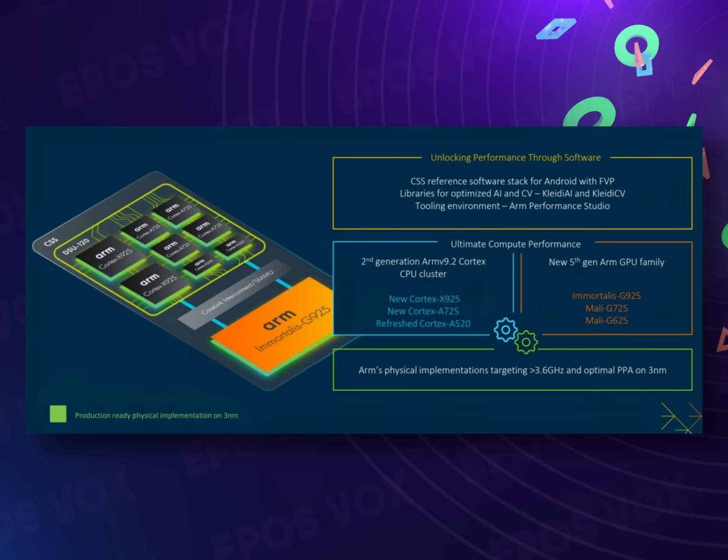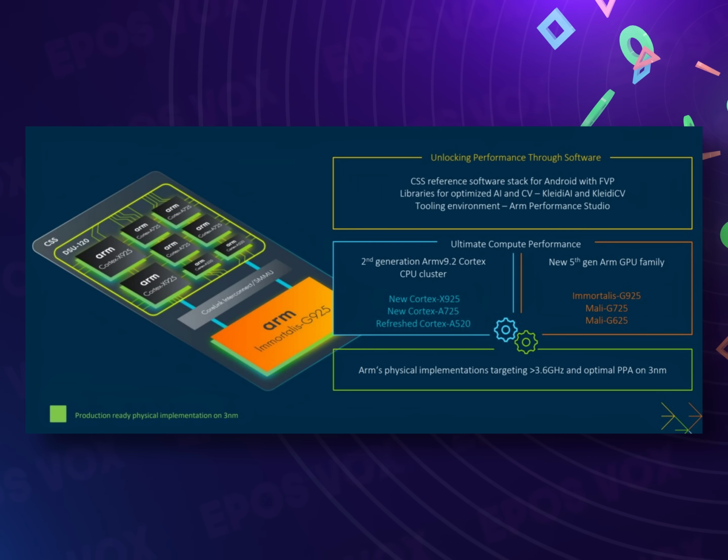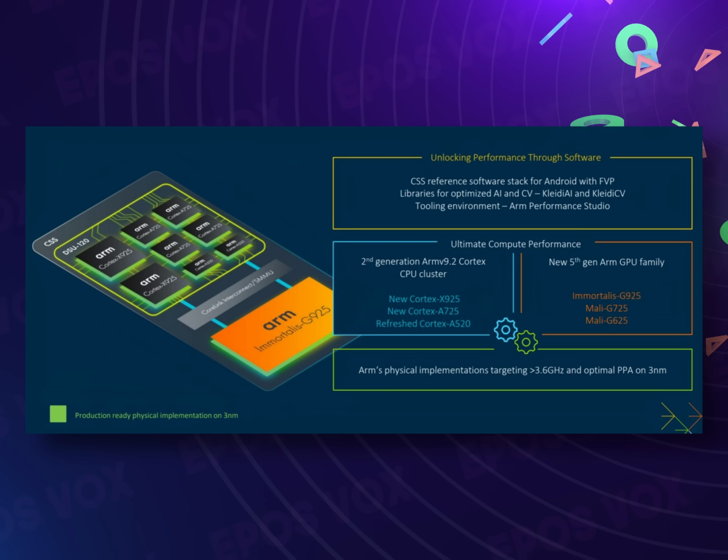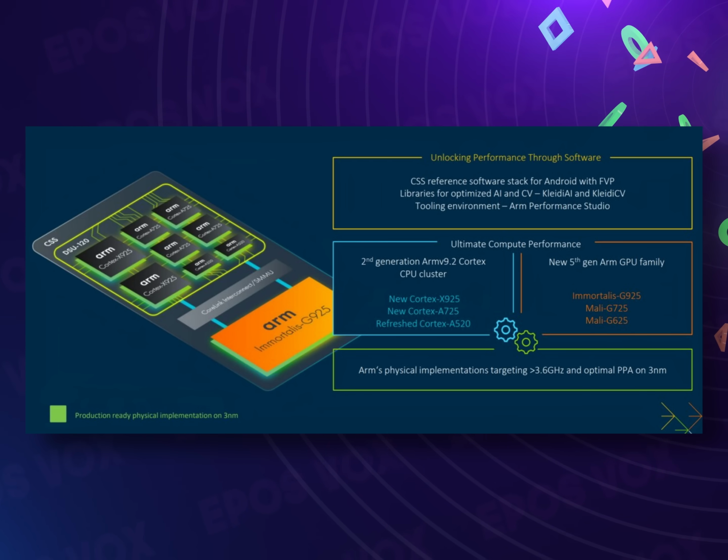But in an SoC system, like a smartphone, you will often see two different kinds of CPUs for traditional instructions, a GPU for graphics and 3D workflows, an NPU or neural processing unit for AI-related tasks, and possibly even more niche specialized chips like an ASIC or FPGA, plus hardware to control I/O ports and capabilities. Since these devices are closed platforms, meaning the user isn't changing individual components and introducing unknown variables or combinations to the mix, the software can be optimized to take advantage of the entire set of hardware to perform its best. Heterogeneous compute enables a single system to have multiple computing subsystems that either work independently or in parallel on a task.